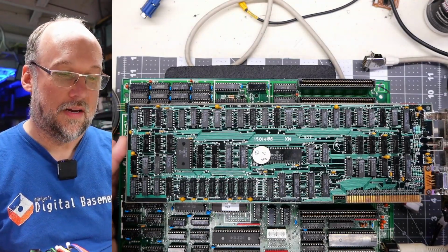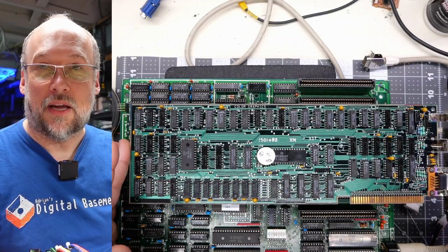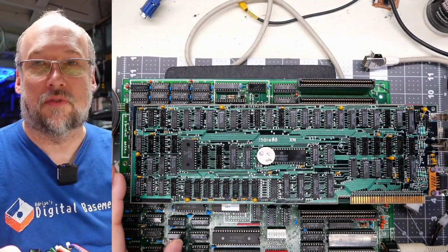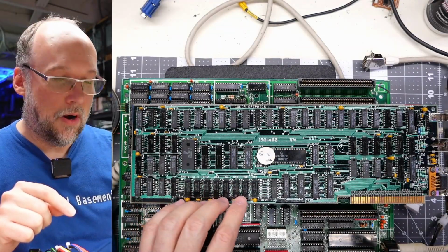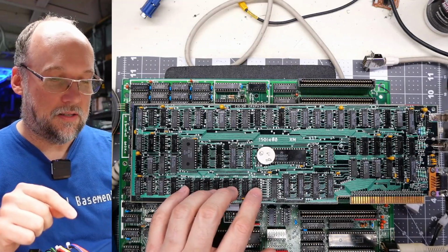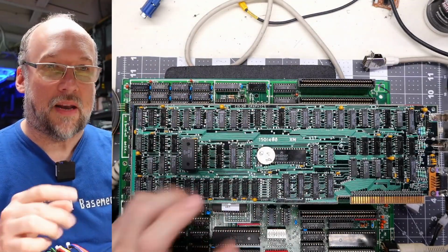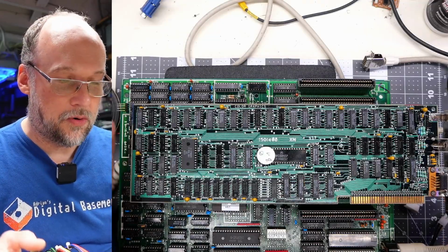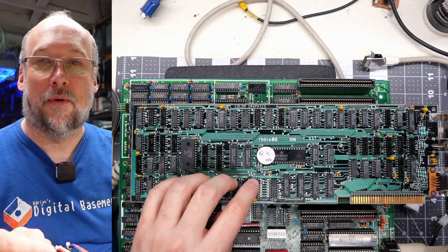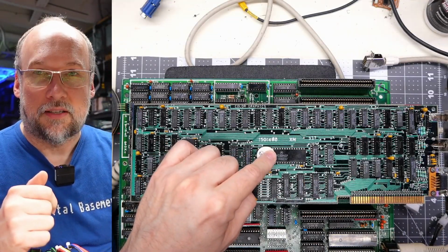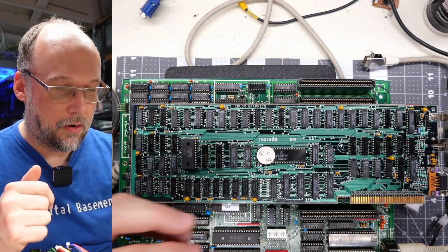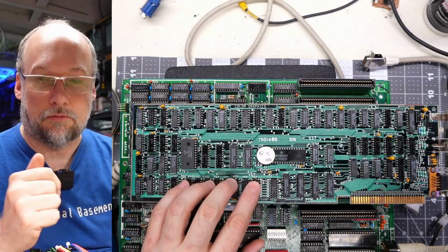So with this original CGA card, when IBM designed it in 1981, they actually had to compromise in a certain way, where when you're displaying 80-column text, which of course is one of the normal modes of operation for the card, the DRAM on the card, which is right here, 16 kilobytes, is used to refresh the entire screen, but it has some contention while in 80 columns mode with the CPU accessing the memory.